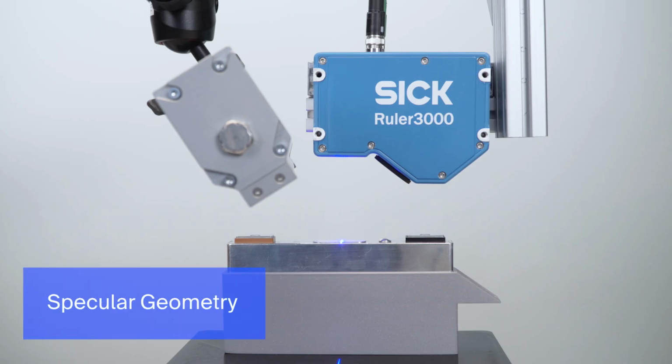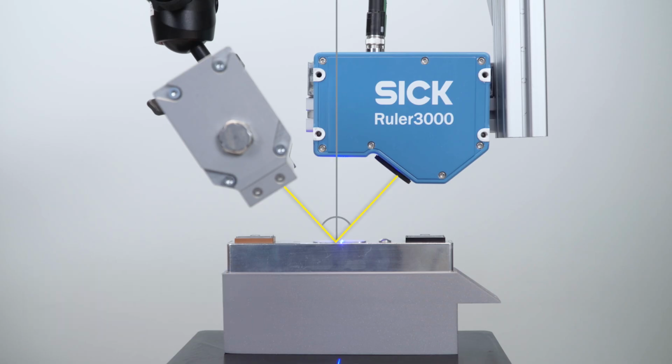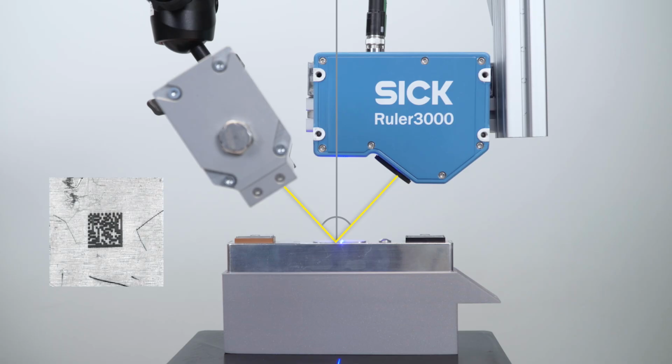In a specular geometry, the camera sees the reflection of the light in the surface of the object. The reflected light will be very bright as it is reflected directly into the camera. If the surface is irregular, such as in the data matrix code, the light reflectance will be disturbed, so not as much light will be reflected in that area, making it appear darker in the surrounding surface.